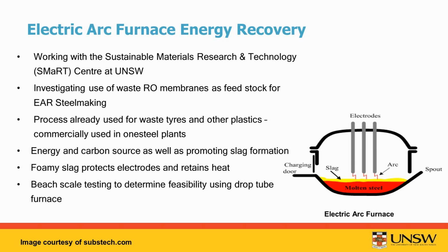So what they strive for is a more sustainable, consistent foamy slag on top of that molten steel to increase the efficiency of the system. And when you start thinking of it in logical terms, you can see that polymers, well, a high carbon component and with hydrogen, provides a very attractive option as a coke substitute. So that's exactly what's been done.